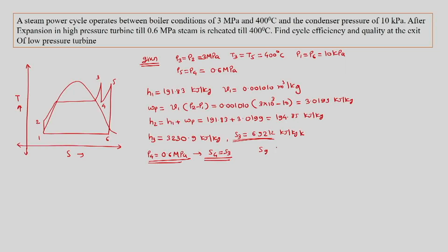In the present case, Sg, the saturation vapor entropy, is less than S3, so we have to find it in the superheated part.